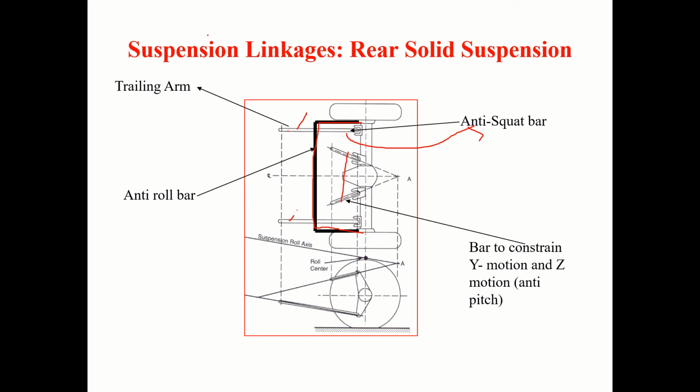Okay, so you have seen these arms in the suspension help in anti-squat and anti-dive design, resisting squat and dive. Then between the arms we use the springs, and that will help in resisting roll moment. So while designing a suspension system, it is necessary to consider all these issues and the linkages have to be designed. When we take the real design, how exactly we consider all these things, we will discuss that. Okay, now thank you very much.